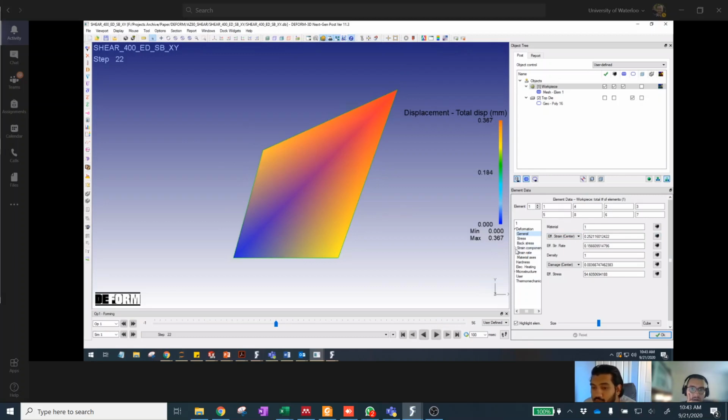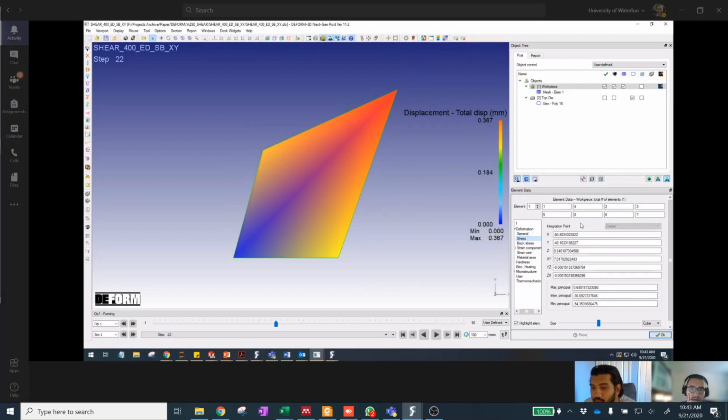So to get the stress components, you have to look at the integration point itself, and this is what I get. So I get the 6 values of the matrix. These are just nodal coordinates, right? Or these aren't the strain? Oh no, these are the actual stresses at the integration points. I think this is like an 8-node brick element.